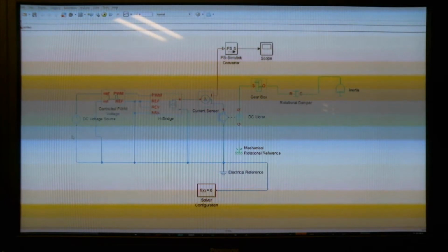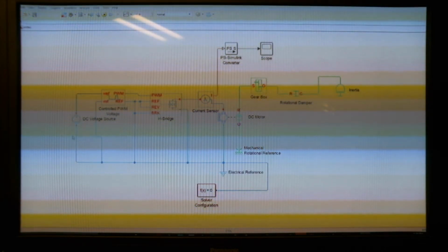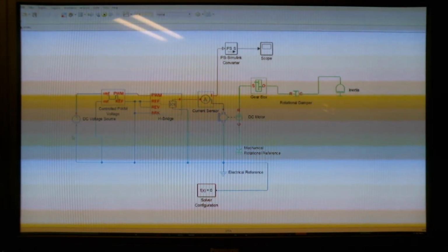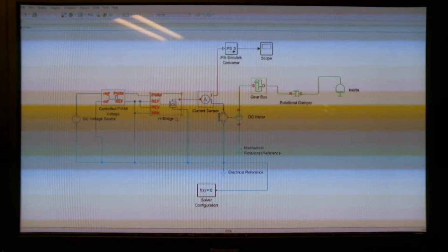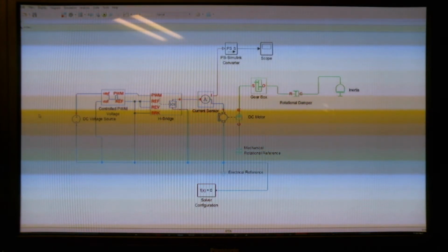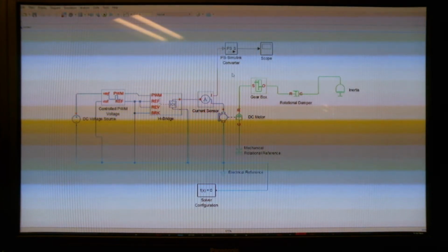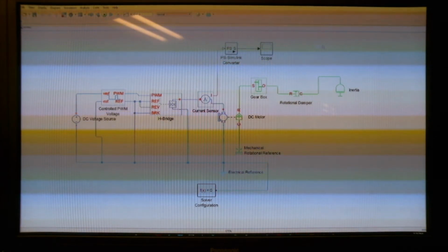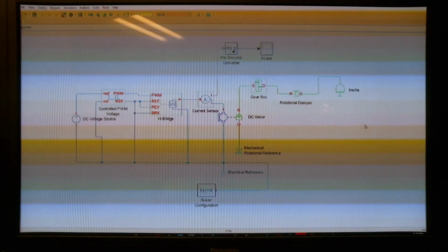With this, you've effectively modeled a very complicated system that if you tried writing all the differential equations out would take you probably a couple of hours to do. This is something that I'd imagine to see on a system dynamics test. But you can quickly model this sort of system using Simulink without having to account for all of the interactions between the electrical and the mechanical side.